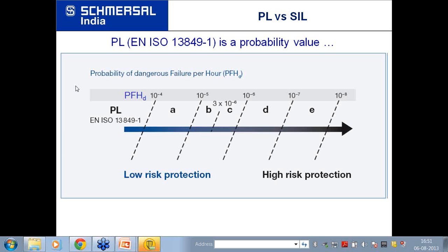Say, if you have an overhead crane in your industry, for the end stops you should always have an electromechanical device, because you can see that the lever is being actuated and the crane is being stopped. There you should not use an optoelectronic device. So application to application it will differ, but in totality, electronic devices are more reliable because they are intelligent.